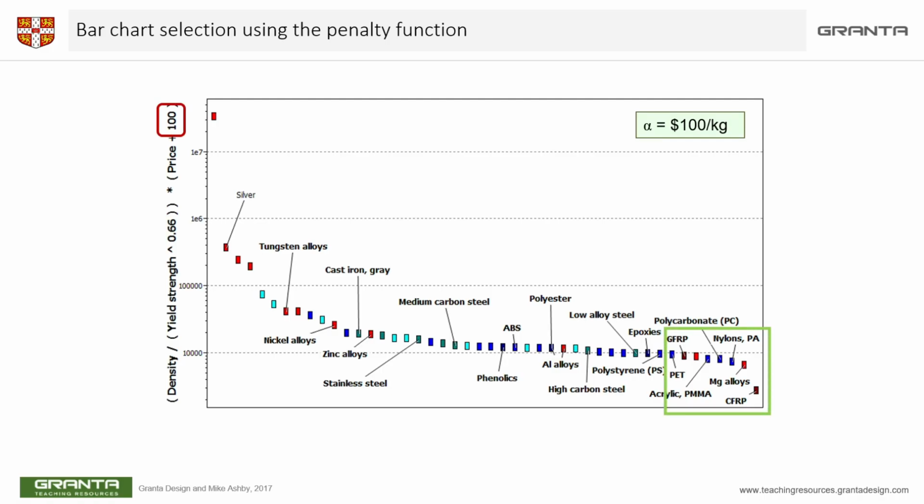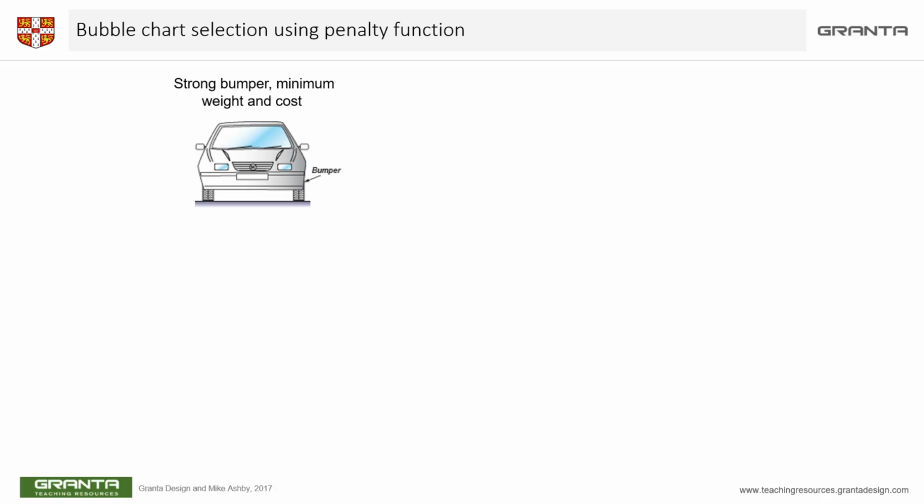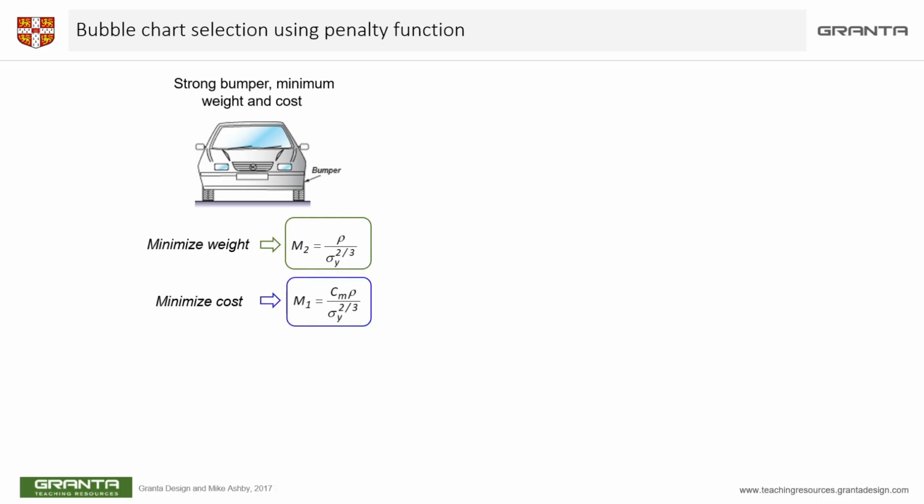This analysis was deliberately kept simple, because I'm doing this in a lecture. As I said, we have to consider other options and other constraints as well. For example, in this case, to reduce the actual impact force, reducing your Young's modulus can also play a role. So you have to look at this from the point of view of the stiffness constraint as well. That's also important. So ideally, you'll be running this analysis as multi-constraint and multi-objective.